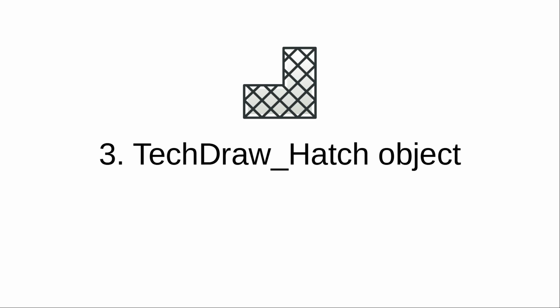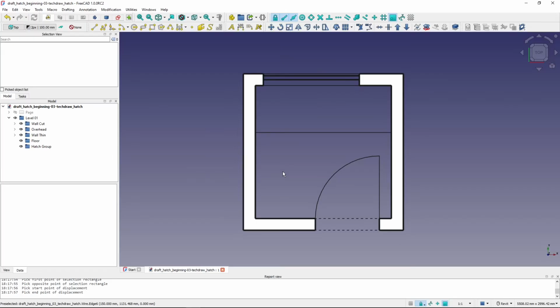Now, let's take a look at the third option, how to create the hatches, and that is using TechDraw hatch object. I'm again starting with my original file with the floor plan without hatches, and here I will not be creating the hatches inside of the 3D view, but I will create them on the page.